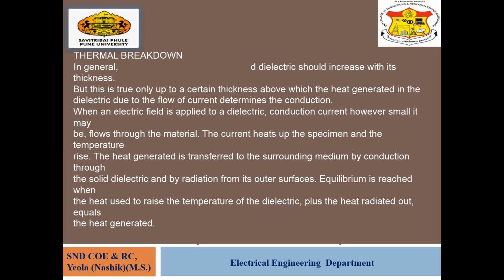It means that we can increase the thickness because the dielectric strength of a solid dielectric increases with thickness, but there is a limit. If this limit is crossed, and the value goes above a certain thickness, then heat generated in the dielectric due to the flow of current determines the conduction.